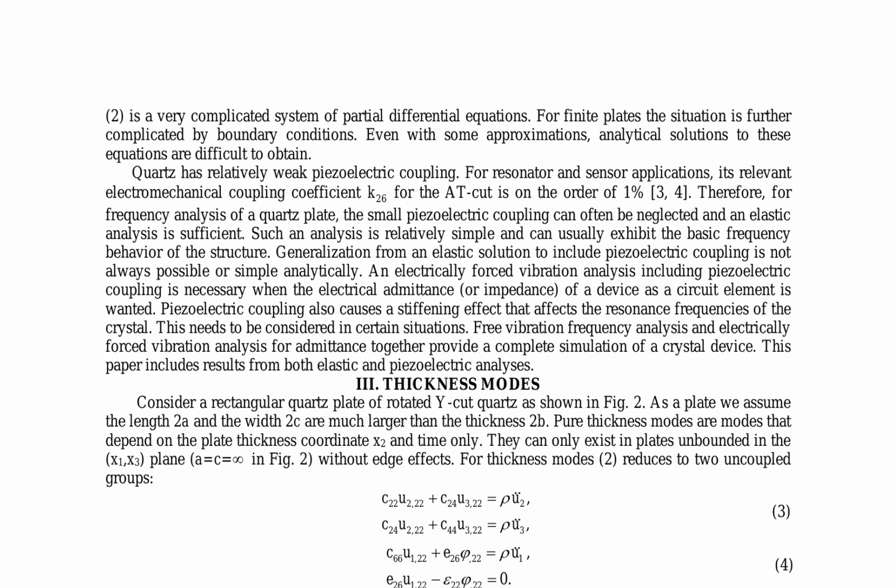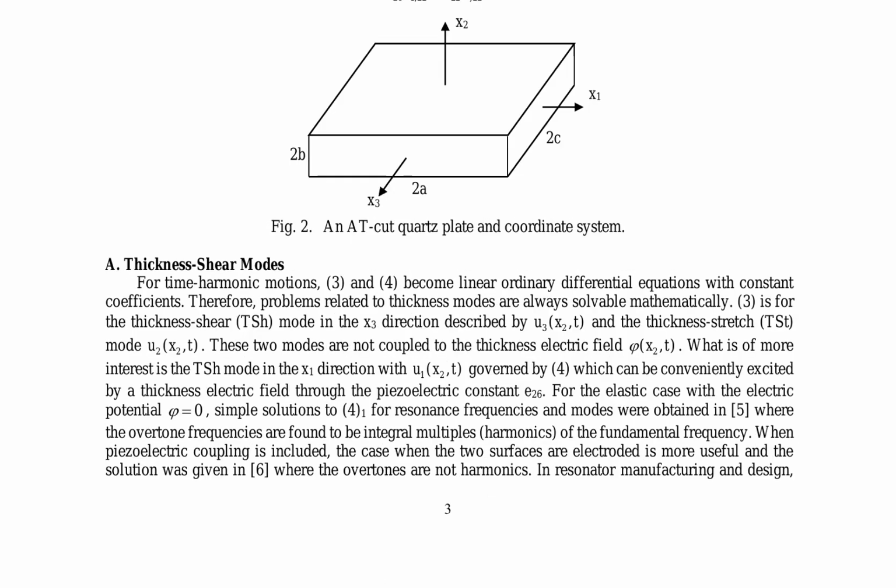Nevertheless, an electrically forced vibration analysis including piezoelectric coupling is necessary for simulating a crystal device as a circuit element. Thickness modes in a rectangular quartz plate are considered, assuming the length and width are much larger than the thickness. Pure thickness modes depend on the plate thickness coordinate and time only, and can be decoupled into two groups of equations. For time harmonic motions, these equations become linear ordinary differential equations with constant coefficients, making them mathematically solvable.